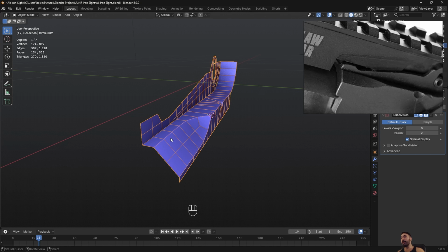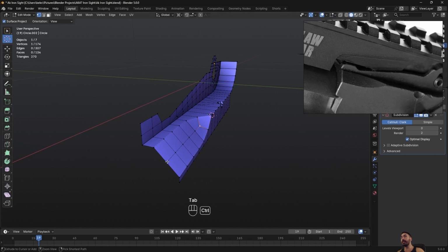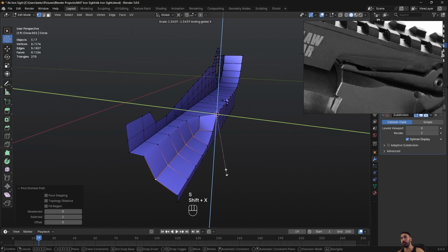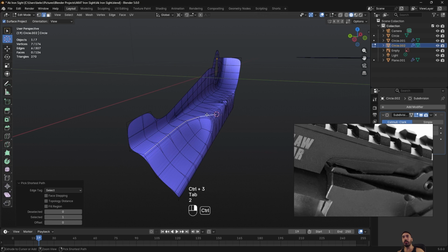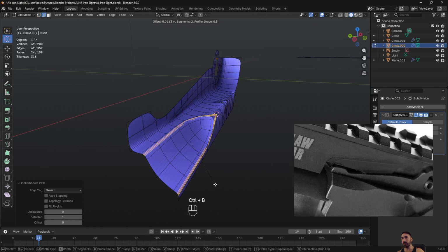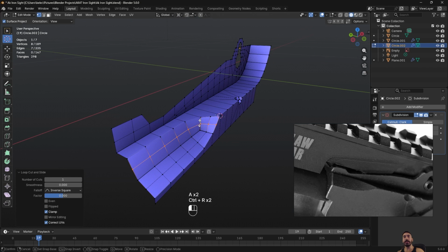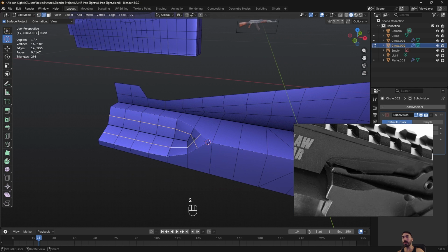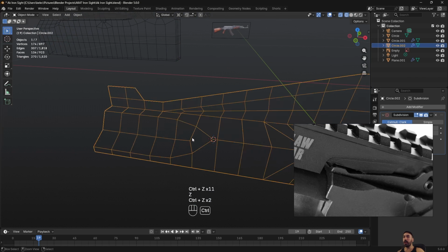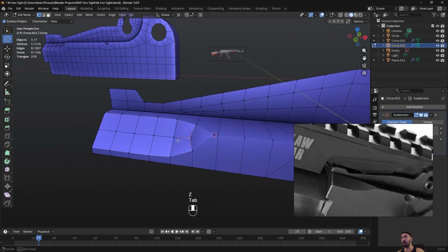If you wanted to make this part curved here, you could take this edge segment here, you could scale that up as well. And with the subdivision surface modifier, that would look a lot more beautiful than it does right now. Or if you wanted to, you could also add some extra geometry like this using loop cuts if you want to deal with that, but I don't want to do that. And my shape is just supposed to be straight, so I'm going to keep it like this.